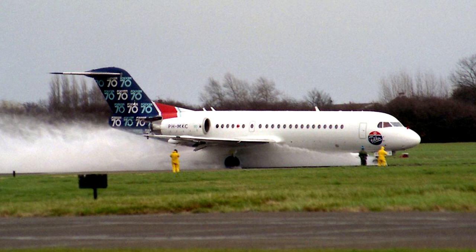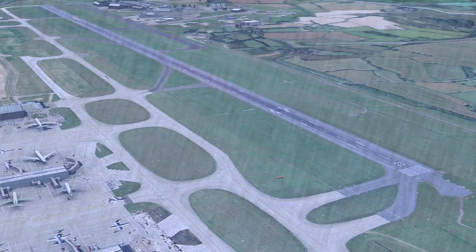The greater the thickness of these substances, the greater the impingement drag, and therefore the greater the increase in the takeoff distance. In fact, there may be so much contamination on the runway that the acceleration of the aeroplane is insufficient to safely get it airborne before the runway runs out.